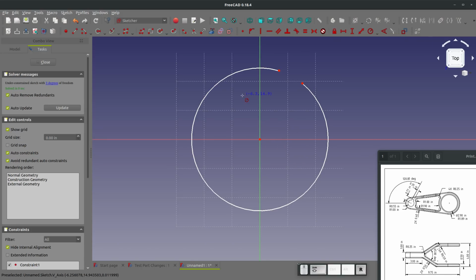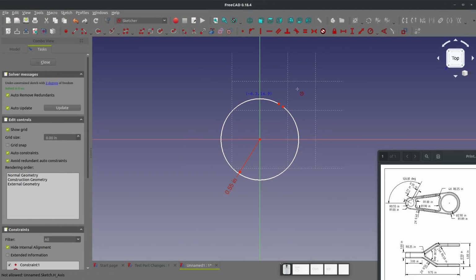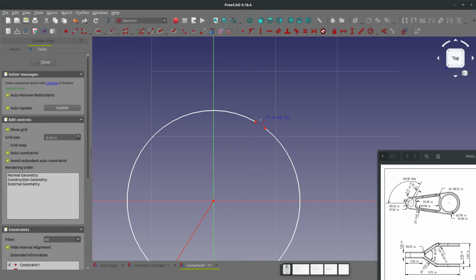or arc, 3-point arc. We'll say Shift R, and notice my keyboard monitor down here if you need to know where your hotkeys are. We're going to give this 0.55. Now we'll grab a regular line. You can use polyline too, but regular line seems to work pretty well. I'm going to choose these 3 points. We'll go with parallel. We'll go with perpendicular, and E for equal.